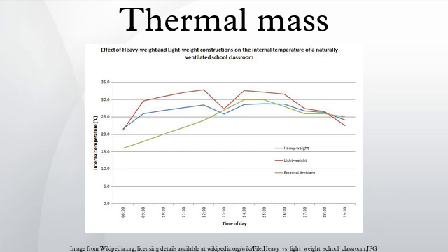For discussion of why the thermal energy storage abilities of pure substances vary, see factors that affect specific heat capacity. For a body of uniform composition, Cth can be approximated by m c_p, where m is the mass of the body and c_p is the isobaric specific heat capacity of the material averaged over the temperature range in question. For bodies composed of numerous different materials, the thermal masses for the different components can just be added together.